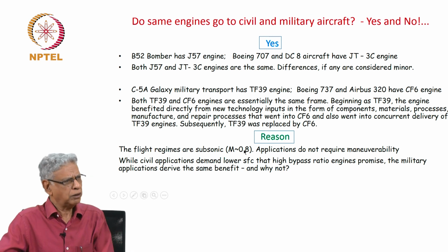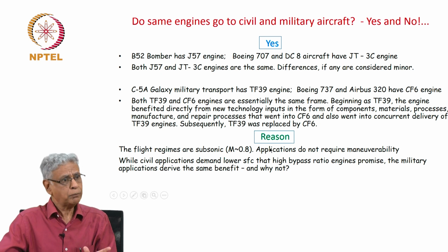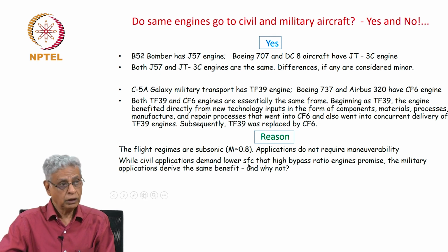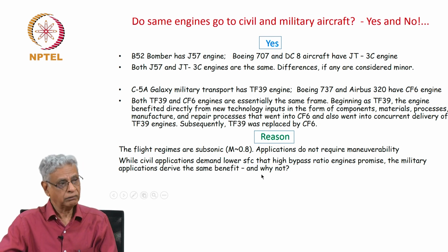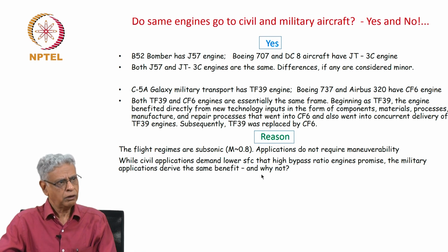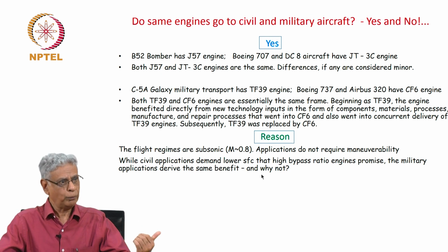The maximum Mach number is about 0.85 and applications do not require maneuverability. So, while civil engines demand lower specific fuel consumption that high bypass ratio engines actually promise, the military applications derive the same benefit, and surely, why not, because the flight regimes are not very different, operational procedures are not very different. In one case you carry passengers, in another case you carry cargo.